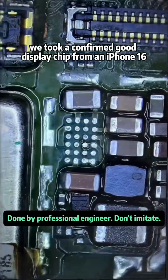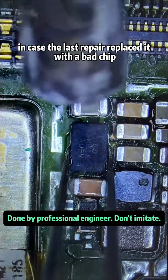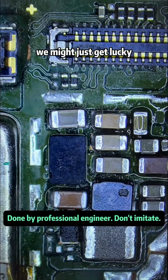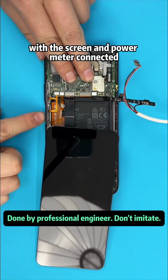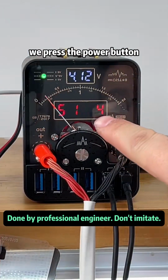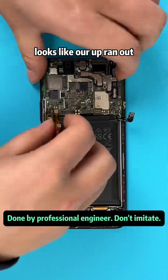We took a confirmed good display chip from an iPhone 16 and installed it. In case the last repair replaced it with a bad chip, we might just get lucky. Okay, we'll reassemble the phone for testing. With the screen and power meter connected, we press the power button. The current indicates it can turn on, but the screen still doesn't display. Looks like our luck ran out.